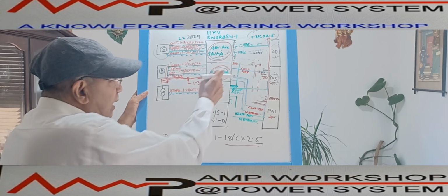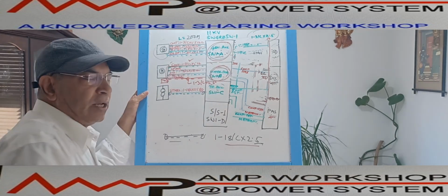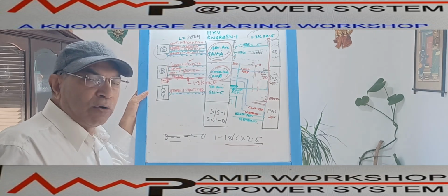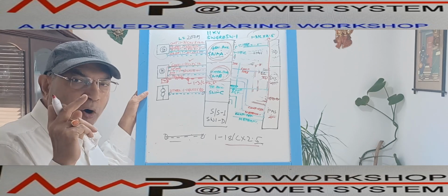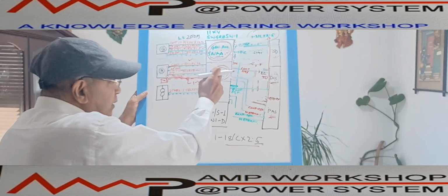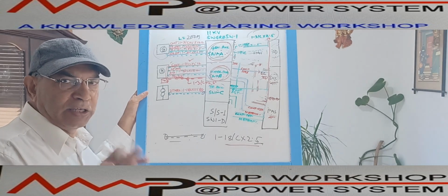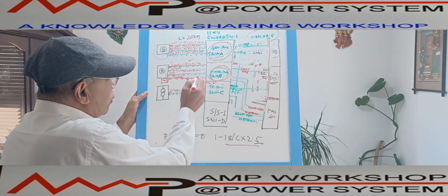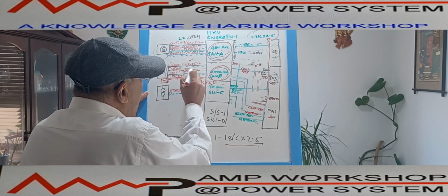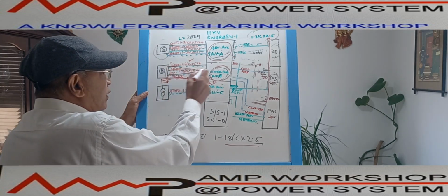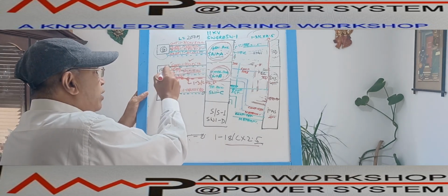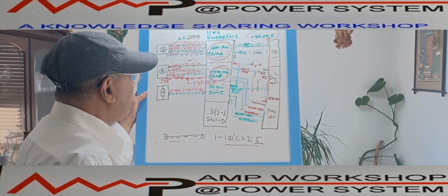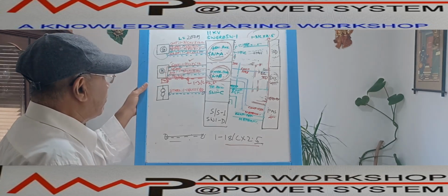So this heater circuit for the motor is getting power from the switchgear auxiliary supply, operated by the breaker auxiliary NC contact. So when the breaker is off, immediately the heater will be on. So there will be one 3-core, 4 square millimeter cable, which is coming from the switchgear and taking the switchgear auxiliary power to heat the motor. So there is another cable for this purpose.